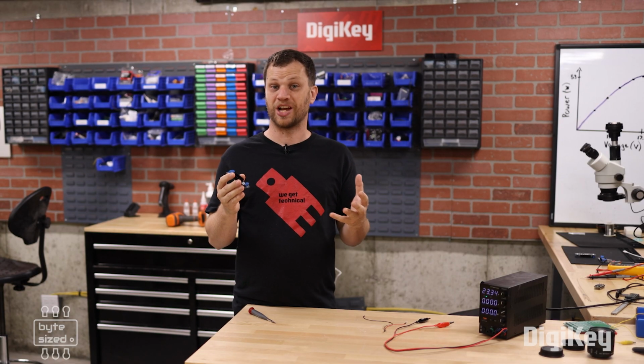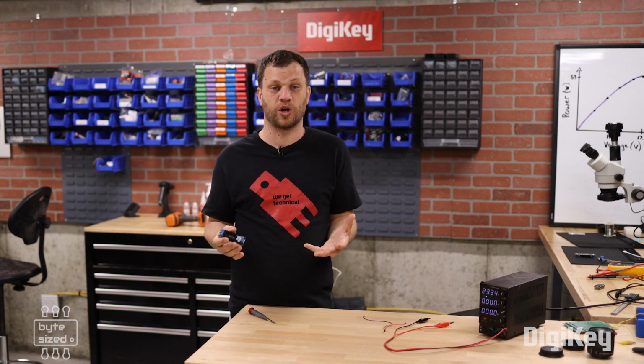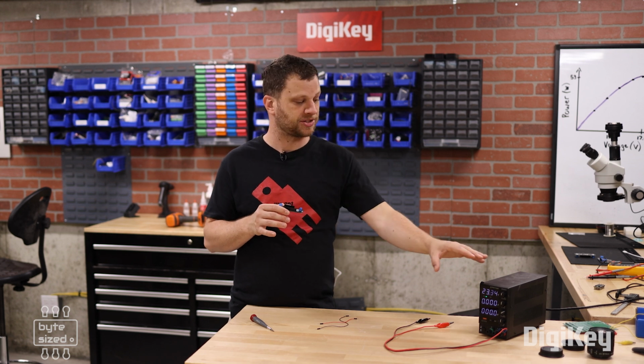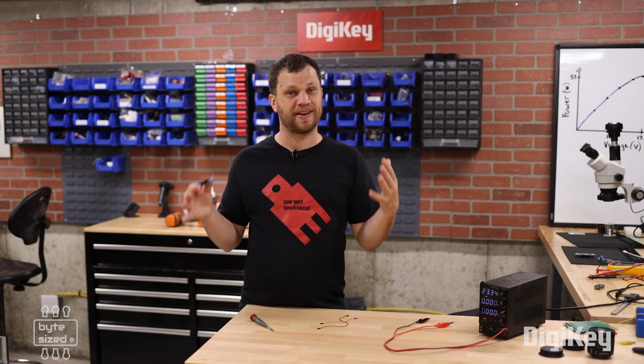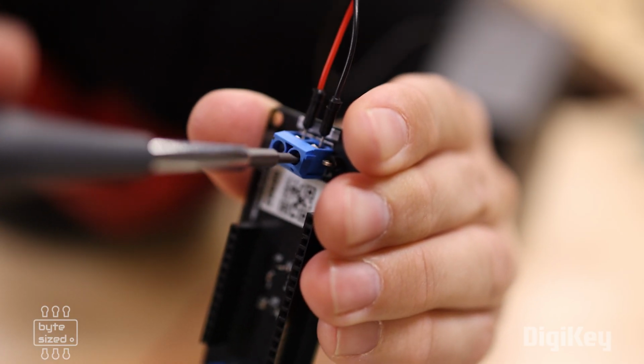Here's the moment of truth. I just finished assembling the custom PCB and I'm ready to test it out to see if it works. Instead of immediately connecting this to a solar panel, I'm going to use a benchtop power supply. It's worth mentioning that a benchtop power supply doesn't have the same power characteristics as a solar panel, but it'll work just fine for testing purposes.